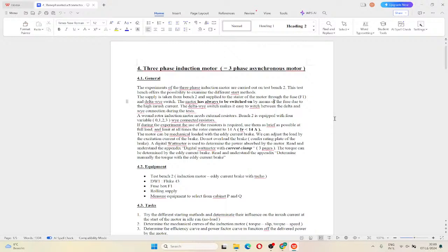Good. But it is also mentioned in the document that it's normal that there will be a lot of difference between each measurement. So we measure it 3 times, then take the average, and then divide by the square root of 2, because it's an RMS value. So, any question about this test? Okay, then we go to the load test.